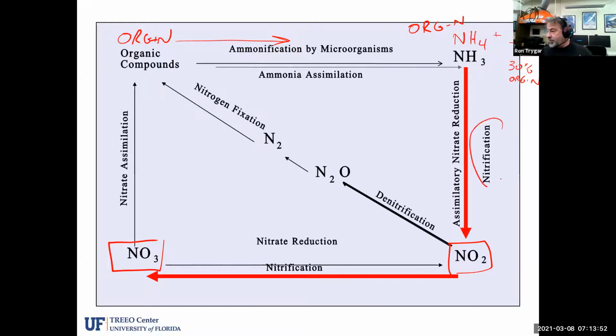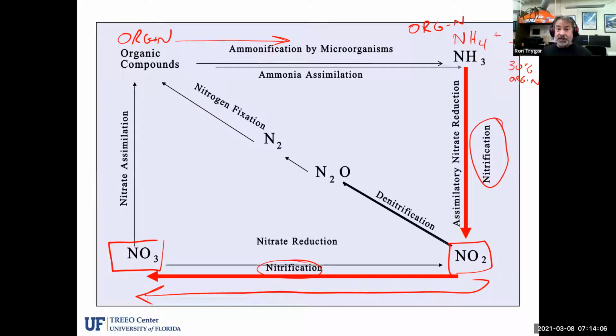All right, so we're coming into the treatment plant, and this word, nitrification, takes place. This is step number 1, and this is step number 2 at the bottom of the chart. So we go from ammonium to nitrite and then to nitrate. And that's the 2-step process. This is called an oxidation process. So this is oxidation, and this is oxidation over here. With the word oxidation, I hope you're putting in your mind that this includes oxygen, or that we have to have oxygen present for these bacteria to do their job.